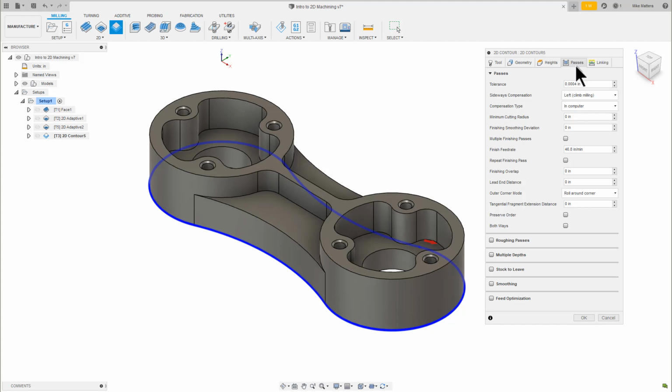2D contour is almost always used as a finishing cut. This means we need to hold the final size based on the tolerance and the part requirements. While Fusion will calculate the toolpath to the highest resolution that the machine can accept, there are factors that can make holding that tolerance difficult during the machining process. Tool wear is the biggest problem in controlling the tolerance at the machine tool.